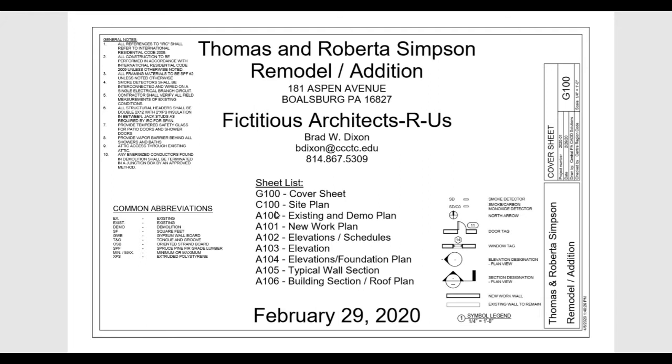And the next one is going to be the C100, the site plan. And then we're going to go down through and it's going to have all of the A sheets as well. So there's a lot of information that's built into this sheet numbering system. Basically the G that starts this out stands for general information. So it's going to be general information that applies to the entire project typically. We can get into this more later, but basically all this information on here is going to apply to the entire project.